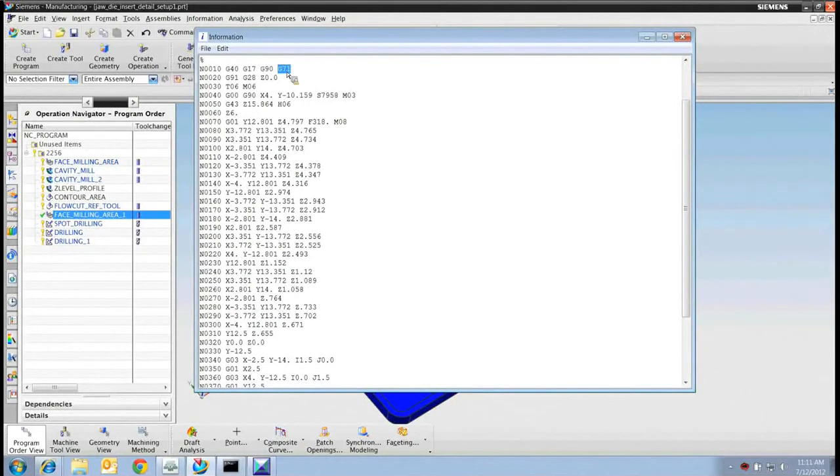About half the machine tools use G70, G71. The other half use G20, G21. So I want to change that to G20, G21. And I also want to move that to the front of the list. I want to move G90 right after that. Then when we get that proved out, we'll come back and take a look at how to put some information about the tool into the toolpath listing.